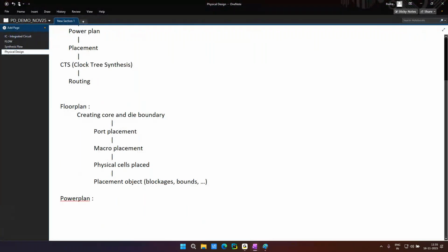So in power planning, distributing the clock network. Sorry, power network. My bad. Distributing the power network such that you will face less EM and IR drop. Here the terminologies that come up are rings, straps, rails, bumps. All these keywords will be coming. Okay. Next, you can say EMIR also.